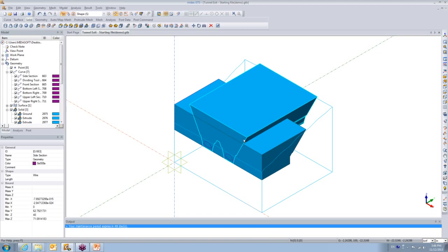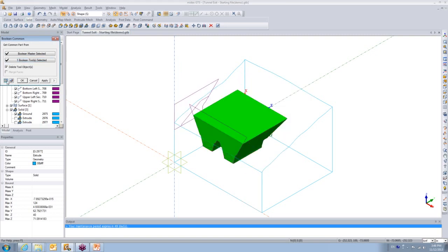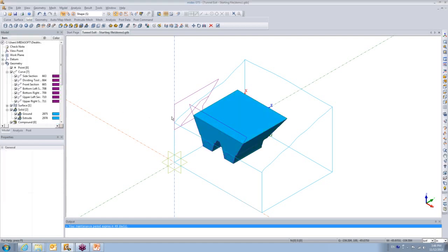And now obviously this is not how it looks like. I'm using these solids to generate the exact profile here. So I'll take out the common part. Just like we do in mathematics, we have Boolean operations. We'll apply the same operations here. So we'll go for a common part. We'll select shape 1 and shape 2 and then say preview. So the program will take out everything else, leaving the common part behind, and I'll say OK.